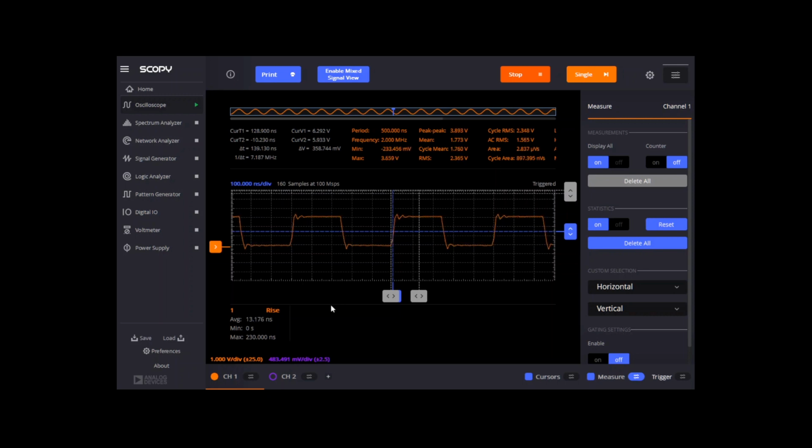So next, I think we need to look and see what the Siglent oscilloscope shows. One thing to keep in mind is that we did see a difference in rise time between the lowest and the highest drive strengths. So that suggests that the Raspberry Pi is really having a rise time of its signal that's at least no more than 12 nanoseconds or so. So it'll be interesting to see if the Siglent shows a smaller rise time.